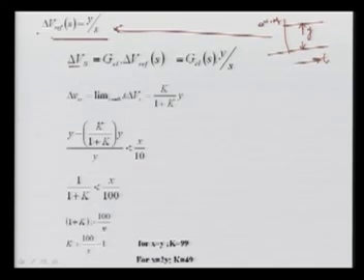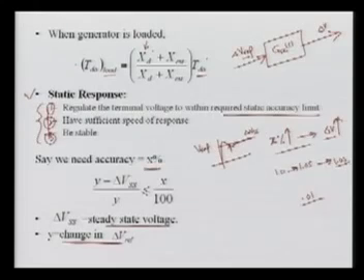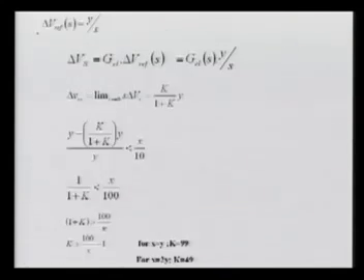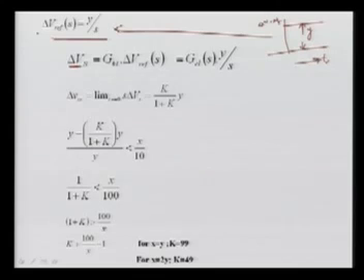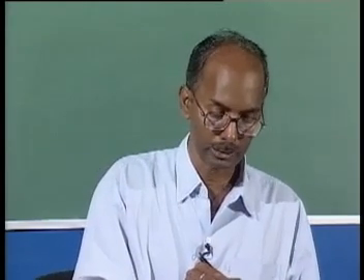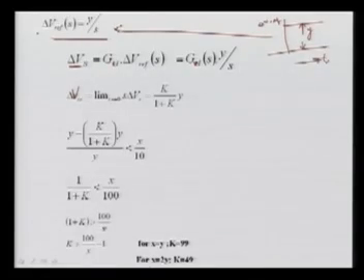Your output from this equation will be equal to this reference change in the Vref multiplied by your closed loop transfer function. So here I have written this GCL multiplied by your change in Vref. This GCL is CL multiplied by Y upon S, and we know our limiting value theorem, that the final steady state value of this voltage, VSS, will be the limit S tends to 0 of S multiplied by the change in Vs.